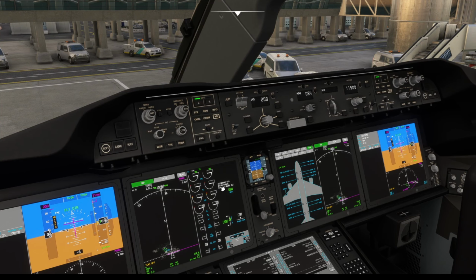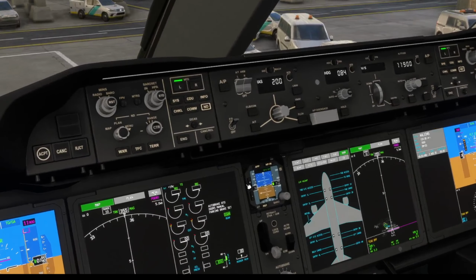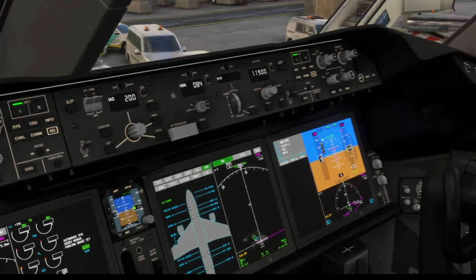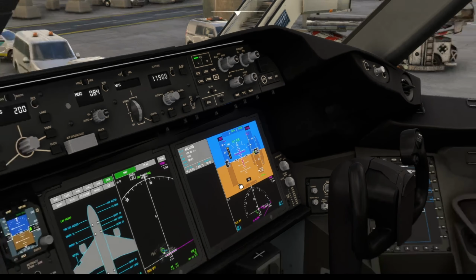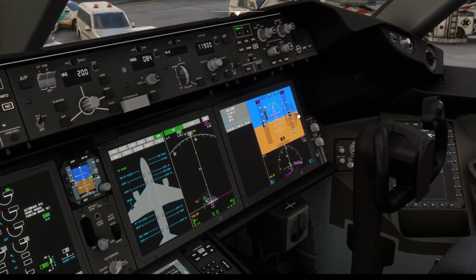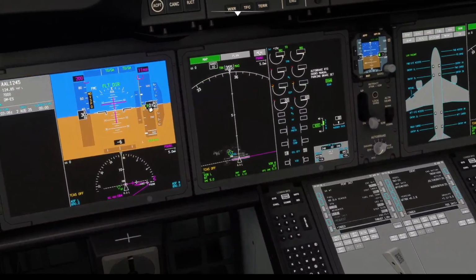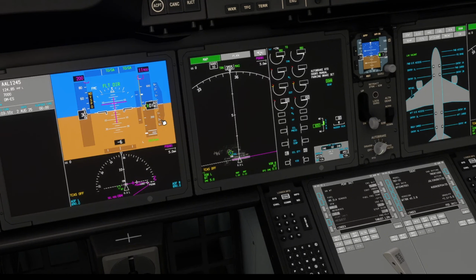Auto brakes RTO, also indicated here on the ICAS, and we make sure altimeters are set correct. And the DFO would also switch to, oh okay, it's already set at 1019. And usually we would check here on the ground that both altimeters read the same thing within some tolerance. So tolerance on the ground should be maximum 75 feet.